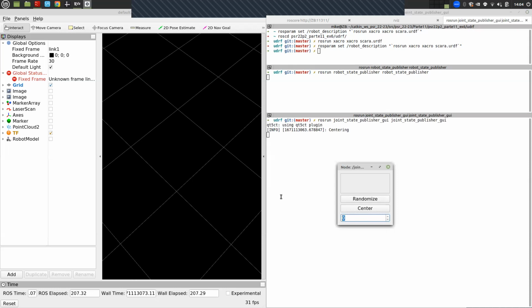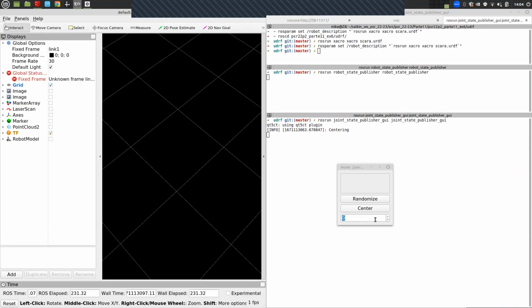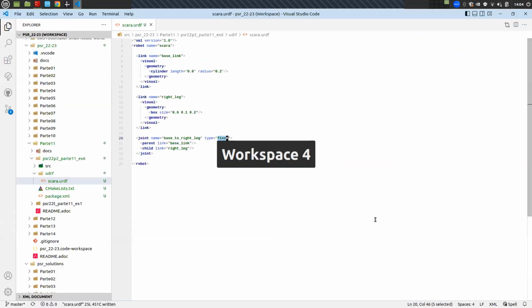And it has nothing because of one particular question now here, which is, I'm only able to move joints which are dynamic. In the case of my robotic system now, if you take a look at the URDF, it contains a single joint, which is here below, and which is fixed. So because it's fixed, there's no joint to move. That's why my window has nothing to do, okay?